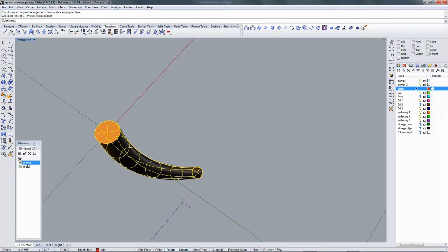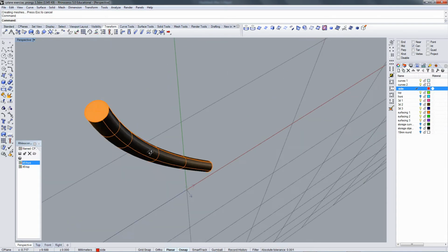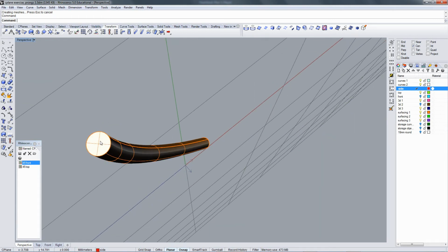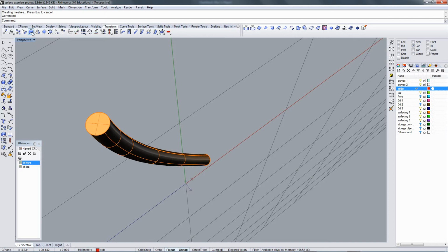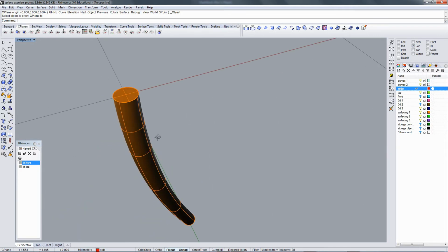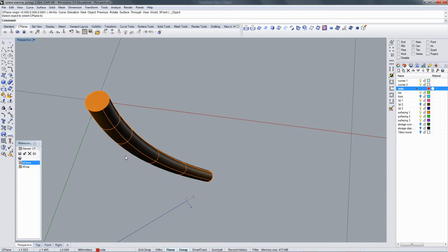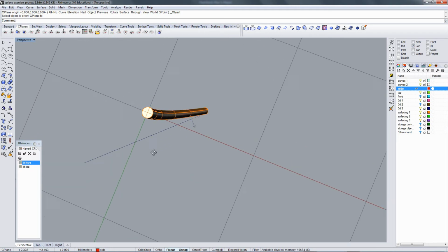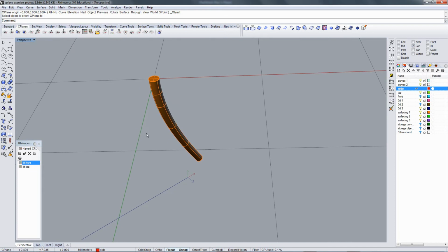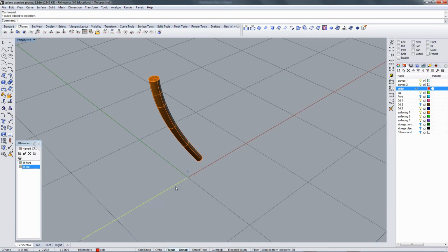Okay. And now I'll go back to 45 front. This is the orientation that I would normally get if I'm using Rhino's set C-planes, which is very upsetting because when I try and set a C-plane to it, I get that, which is not useful. Not useful to me at all. Okay? If that happens to you, you go back to your 45 top.